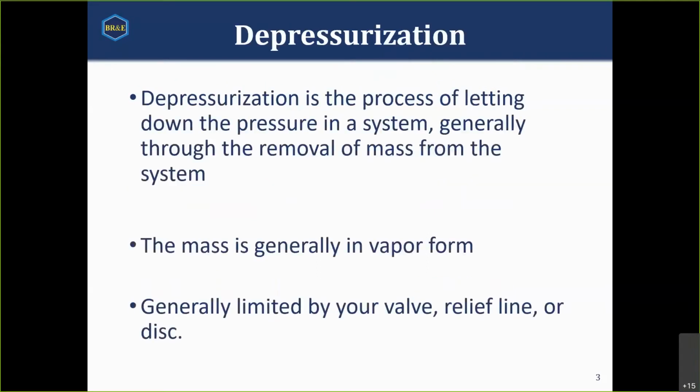So depressurization, just like the name sounds, is the process of taking a system at pressure and lowering the pressure of the system. You usually do this through the removal of mass from the system. If we want to be completely technical, it is not the only way to depressurize a system. You could lower the pressure through other methods. It is by far and away the most common method. So you generally do it, as I said, through the removal of mass, usually through a valve of some kind you have on your vessel.